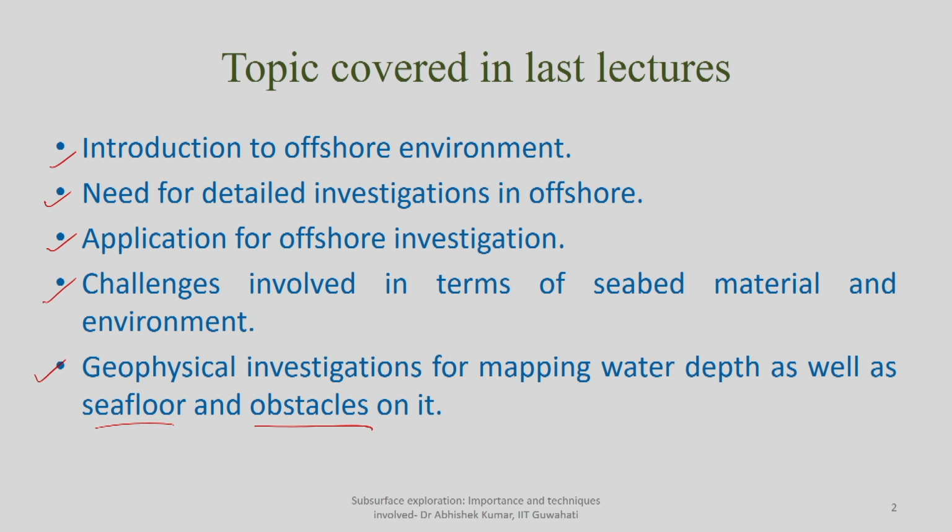More precisely, we discussed the echo sounding method, in which you transmit a sound into the sea environment, and depending upon the time for reflection you get an idea of the water depth. Similarly, if you know your sensor is at a particular depth with respect to the base of the vessel, you can deduct or add it to get the true water depth, depending upon the relative position of the receiver with respect to the sea surface.